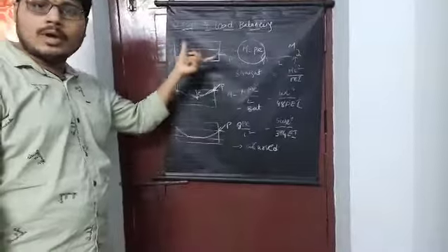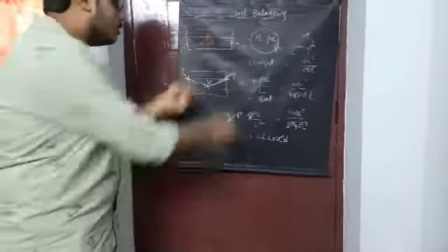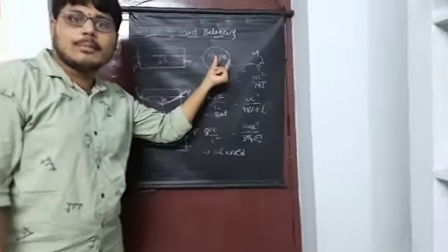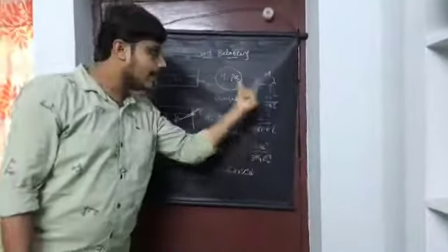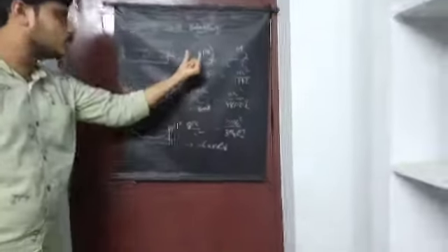First, we have taken the straight tendons. The tendons are placed straight, with eccentricity, in a straight direction. Then the maximum bending moment. In this load balancing concept, we will calculate the maximum bending moment and maximum deflections. The maximum bending moment for straight tendons is known as M.